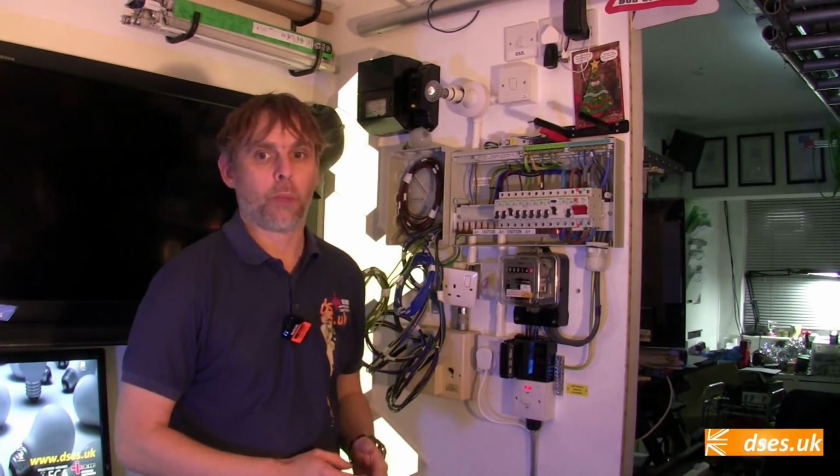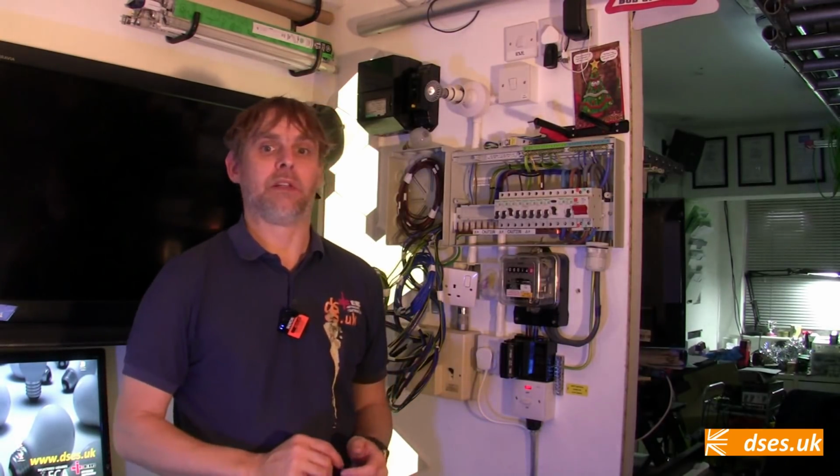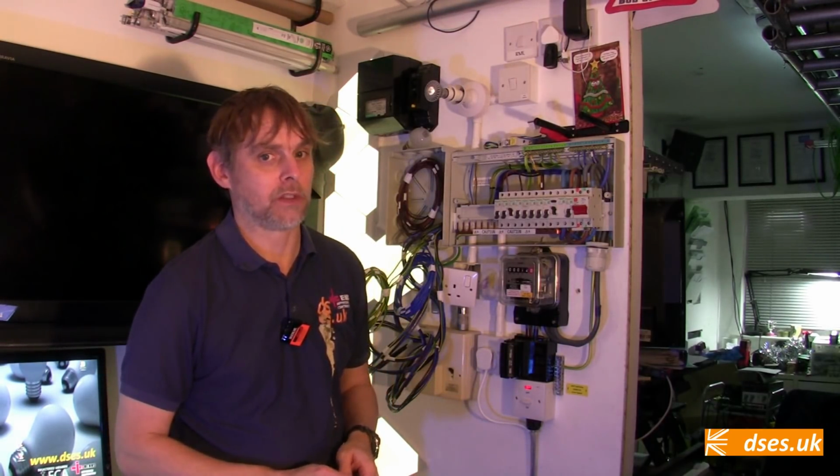So, short of expensive rewiring, what is my top tech tip fix for this? Well, it's easy enough, but don't attempt it unless you're savvy with the screwdrivers. I've shown this is just a stray voltage with no real current behind it, and it just needs a bit of mopping up, and we've already seen that a parallel resistive load such as my voltmeter or even my hand will make it go away. So let's put such a load in place, one that costs nothing to run and will cope with either the capacitive voltage or the full mains voltage when the light is on.